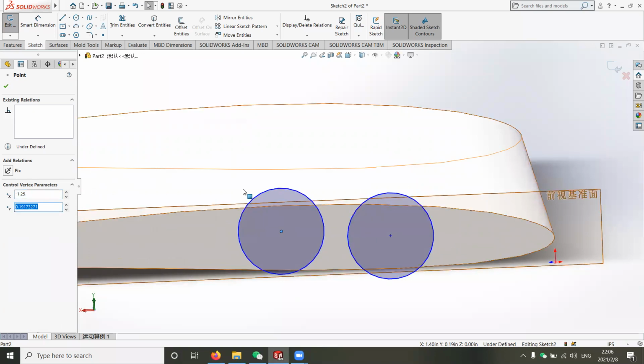And for the y-axis locations, you want to make sure these are about in the center of it. So 0.15 is a good number. Here, it just depends on your airfoil. Again, if you have a highly cambered airfoil, we want to adjust this a little bit. But you do want to make sure these two holes are actually on the same y-axis.